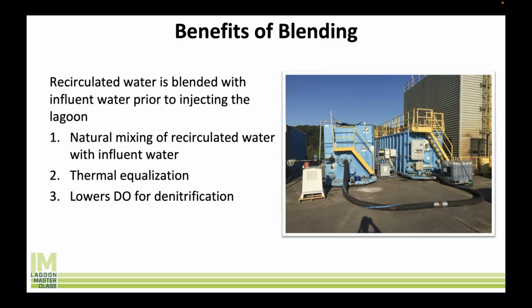And we ran into the problems that I was speaking about earlier, where we come out of the nitrification tank fully nitrified, lots of nitrates, but really high DO, and then we run it into the denitrification tank, and it'd be like, oh man, we can't get this DO down, it's difficult to control the process. We were getting some denitrification in this tank, but we weren't getting all the amount that we needed to get to the really, really low limit that they required.